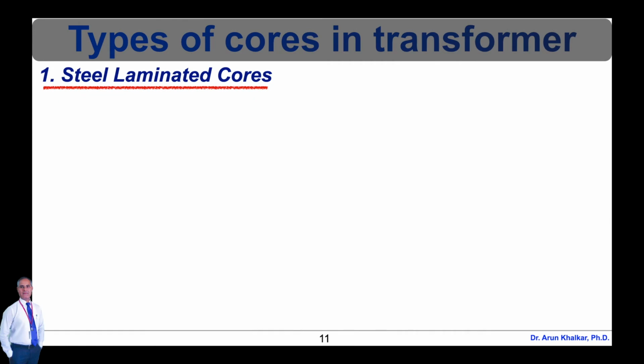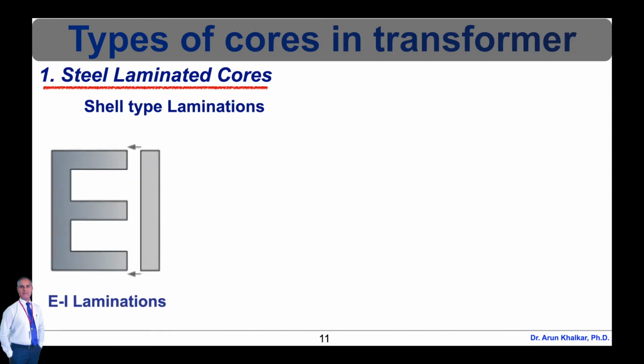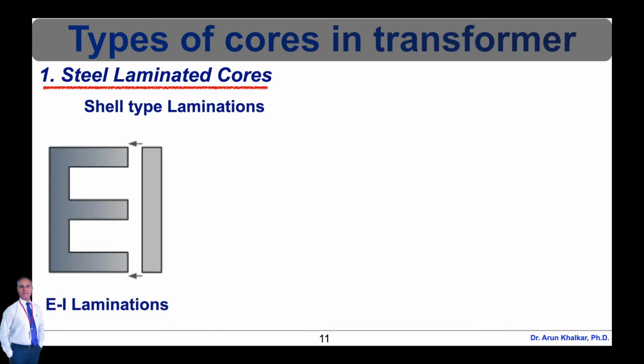You may be wondering how the primary and secondary windings are wound around these laminated iron or steel cores for these types of transformer constructions. The coils are firstly wound on a former which has a cylindrical, rectangular or oval type cross section to suit the construction of the laminated core.